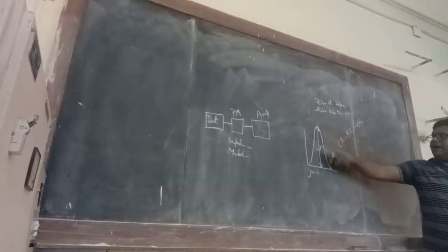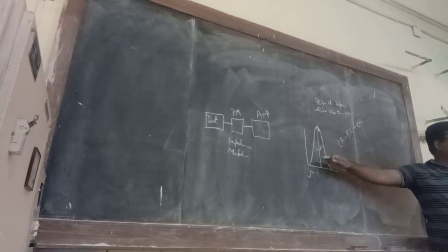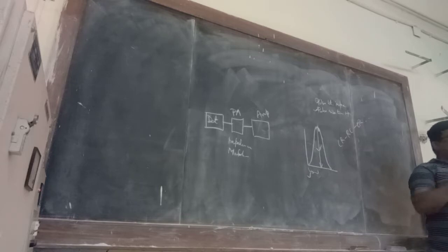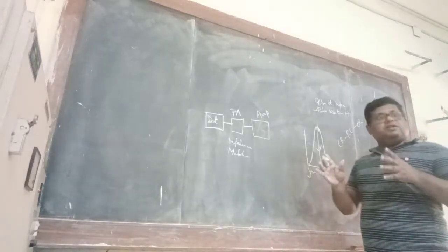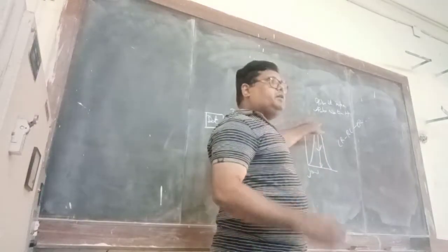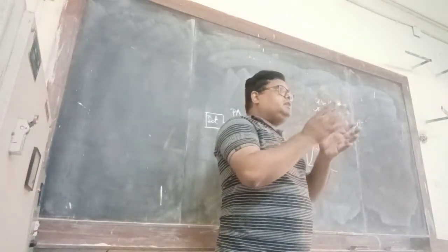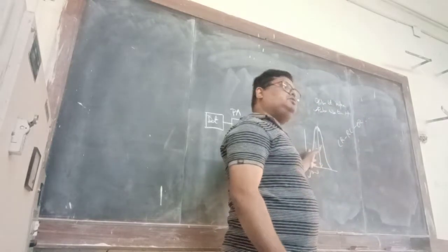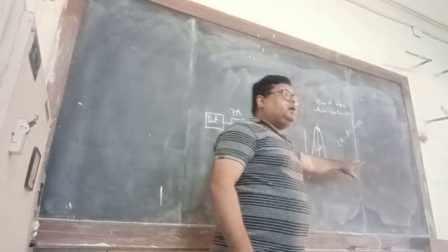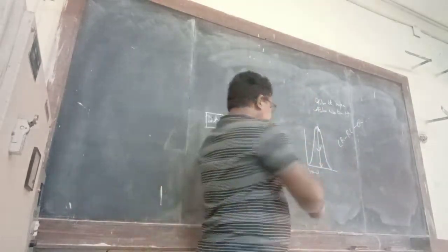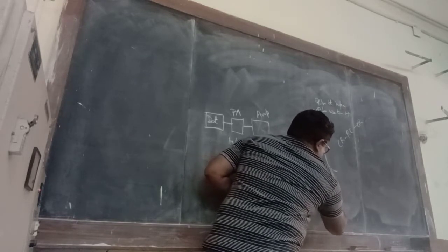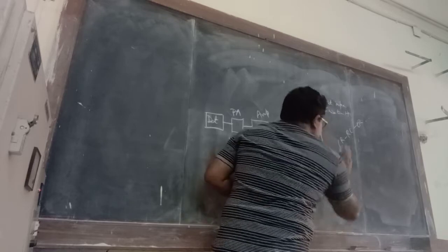You see, this height is basically proportional to the area of the curve. So instead of measuring the area of the curve, which basically is a measure of the energy, we will have this pulse height as a number or as a function of the energy carried by the pulse. Do you understand? So what we will do now is, instead of pulse area spectroscopy, we will do pulse height spectroscopy, or pulse height distribution.